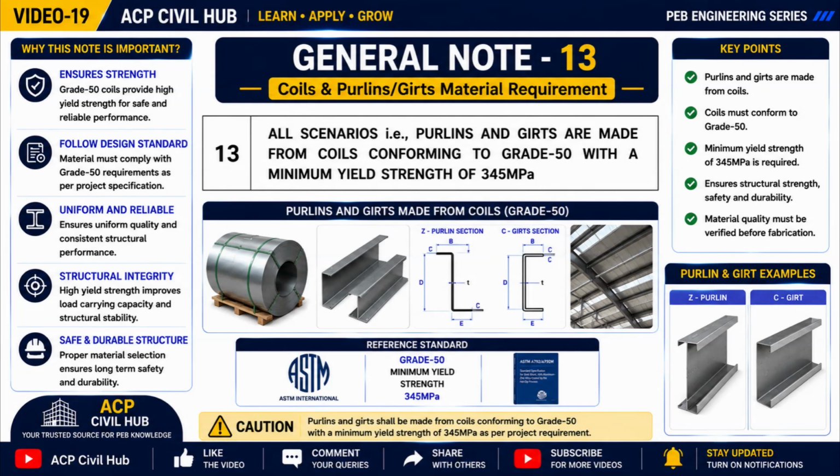Using the specified material improves load carrying capacity, durability, corrosion performance, and the overall reliability of the PEB structure. Always ensure that purlins and girts are fabricated only from approved grade 50 coils with a minimum yield strength of 345 megapascals, exactly as specified in the project drawings and general notes.